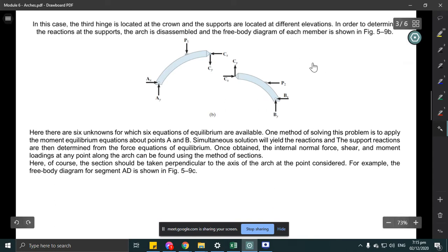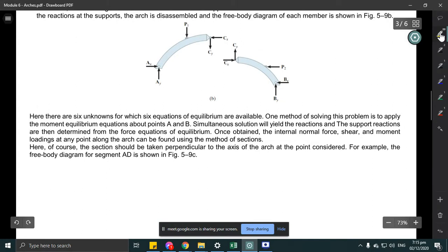So, ayun nga. Kung mababasa nyo kasi, hindi na naalis yung word na equilibrium. Kasi guys, ang application or the equation na gagamitin natin is yung una, kung saan i-analyze natin siya using the equilibrium equations. So, we will apply moment at either of these two supports in order to solve for the support reaction. And then once we find the one reaction, we will take summation of forces X and then summation of forces Y so that we can solve for the other unknowns.